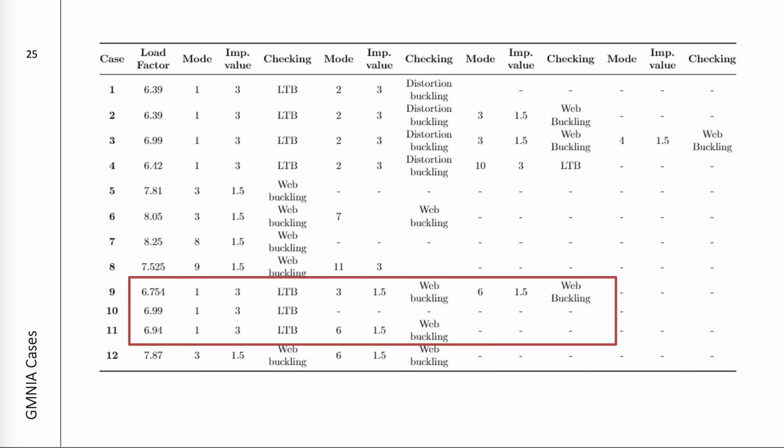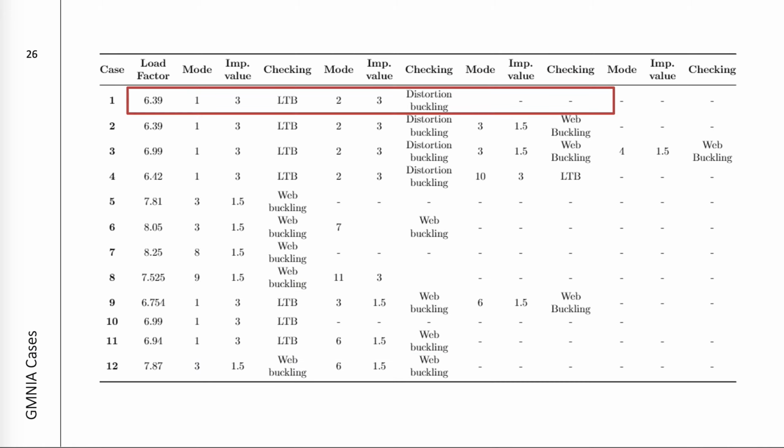While the beam was sensitive to global imperfections introduced in mode 1, it is insensitive to other local imperfections. This conclusion coincides with the LBA, where it identifies mode 1 as being the most critical. Looking back at the 2 load cases mentioned, it is evident that interactions of different failure modes cause the load capacity of the beam to decrease, and that a target load of 13.5 kN was not reached for the most critical case. This conclusion shows the importance of including imperfections in design applications.